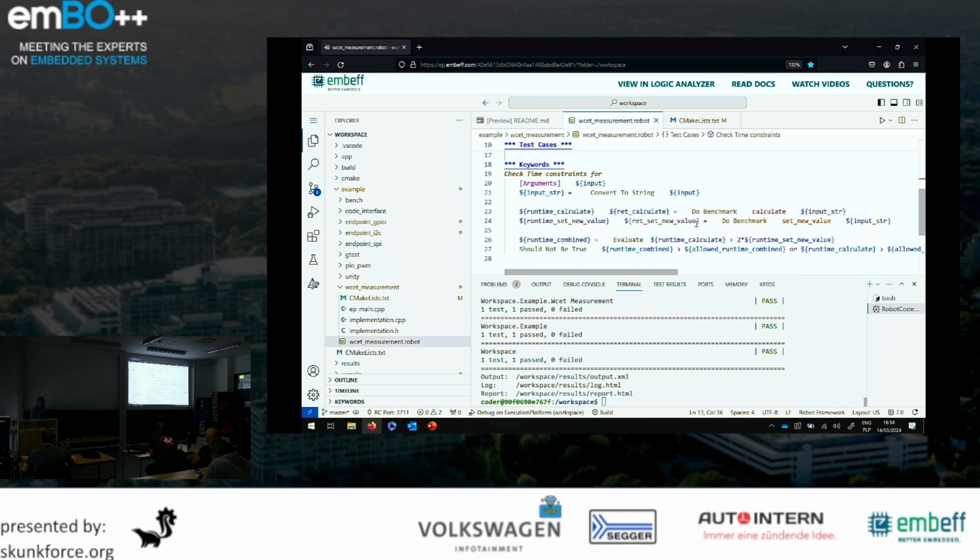The other thing that we can also do is save here and look at the values. The other one was not meeting the 40 microseconds, and I think with this floating point implementation, we are lower than 10 microseconds. So this is how different library implementations, the same for CRC or some other standard algorithms, can be faster, can be slower, depending on the implementation. We can check if this one is better or the other one is better. Or when we have some benchmarks for the library, we change the compiler, we can rerun it again and look if something changes, depending on the environment that we need.